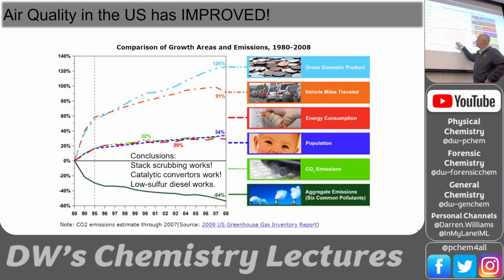And so we've dropped those concentrations of unburned hydrocarbons using catalytic converters. That's a reactive surface in the exhaust stream of a vehicle that these unburned hydrocarbons will land on, and oxygen will land on. It is a catalyst, so it catalyzes the breaking of that oxygen double bond and catalyzes the oxidation of those hydrocarbons. Essentially burning the unburned hydrocarbons on the surface of the catalytic converter. And so mostly CO2 comes out instead of unburned hydrocarbons.